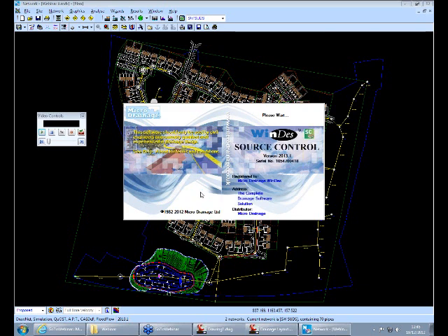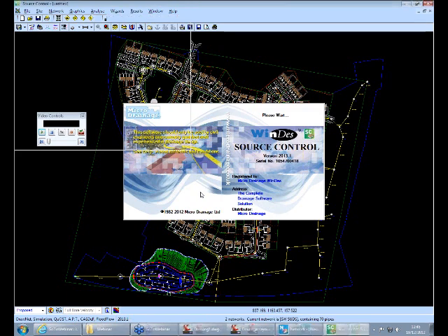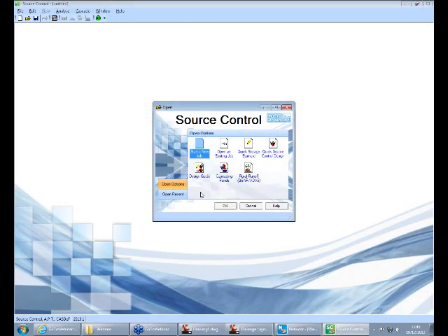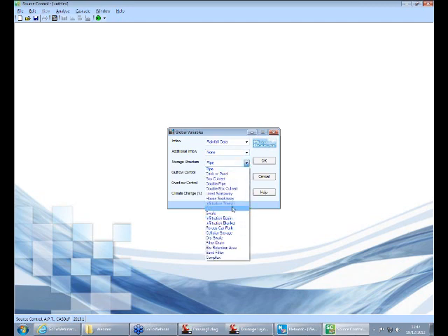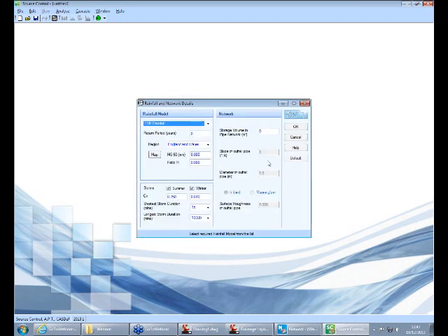What we'll look at sizing up is some basic house soakaways or some small storage structures just to go in the house gardens for some of the properties we're looking at on our design. So we'll go ahead and start a new job, specify the storage structure as a house soakaway, the outflow as an orifice, and we won't have any overflow, so we set that to none. Go OK on the global variables and it pops up the rainfall details.